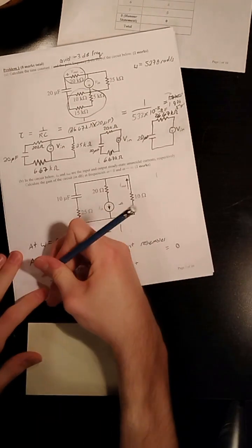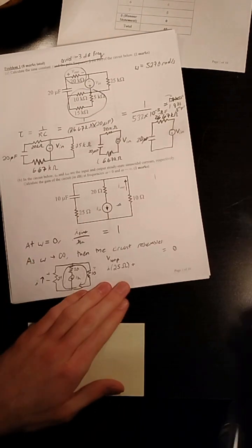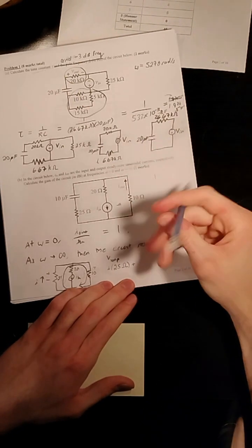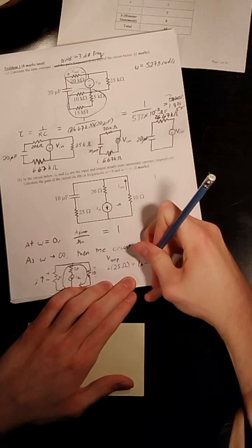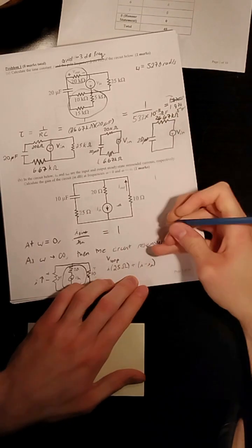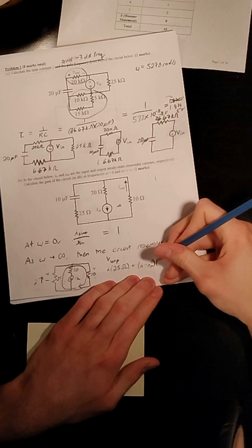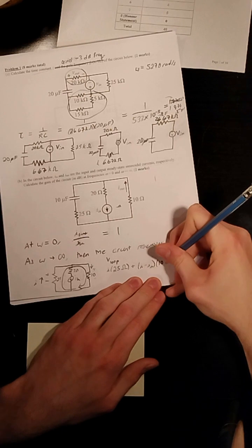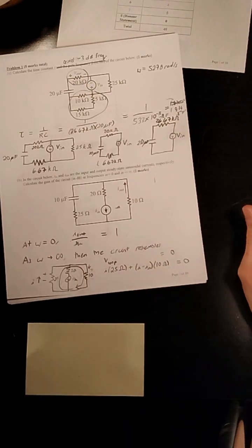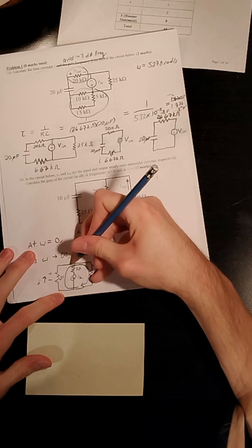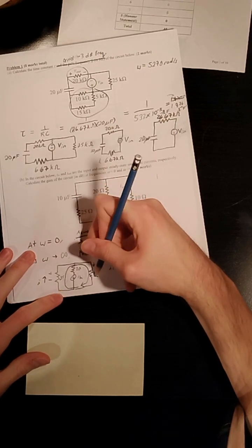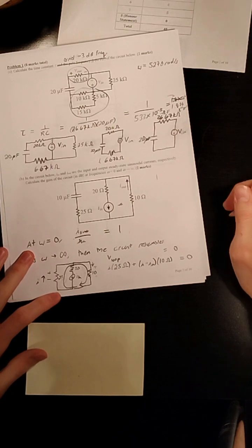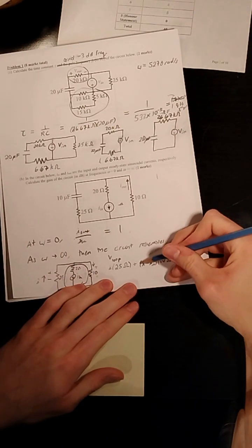So yeah, we'll call the current going this way I, and then plus I minus I in times, and that's the current going down, times 10 ohms is equal to 0. Yeah, because whatever current you had here, you lost I in, and then you're continuing through the 10 ohms. So that works well. And then all we need to do is